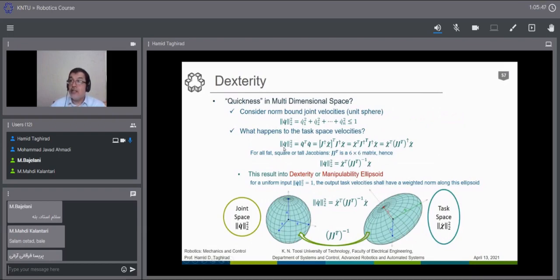Since we have the norm 2 of velocity defined here, we have a J inverse or J pseudo-inverse, depending on being a 6 degree of freedom or more. Not the cobra, not this man, none of them are square matrices. They have more than 6 degree of freedom actuators, but in the general case, we have pseudo-inverse here, pseudo-inverse tau, and pseudo-inverse x dot.